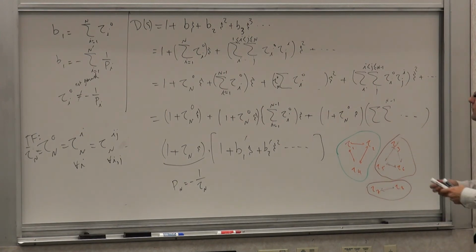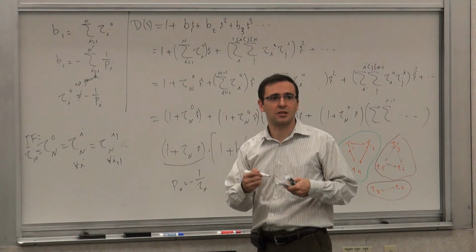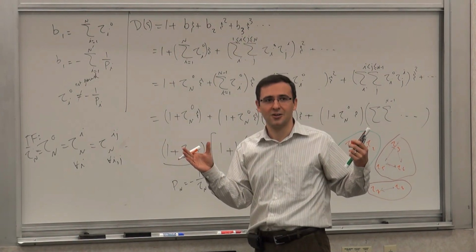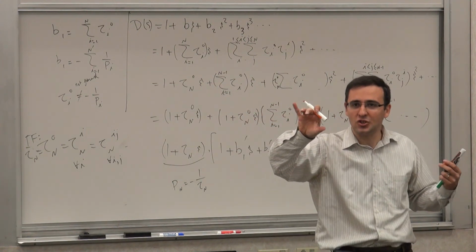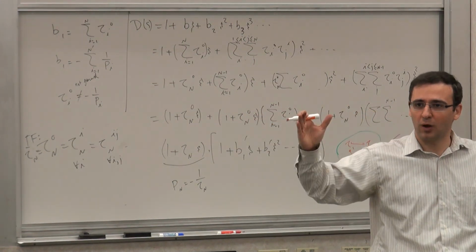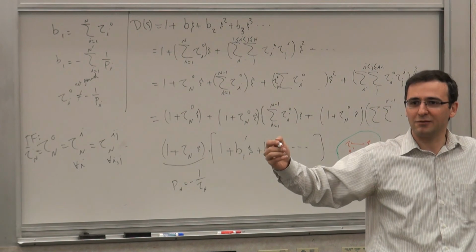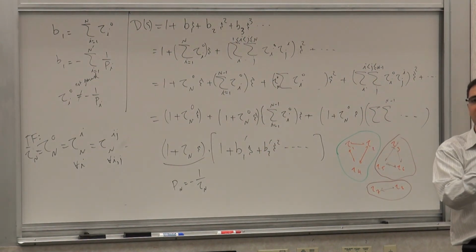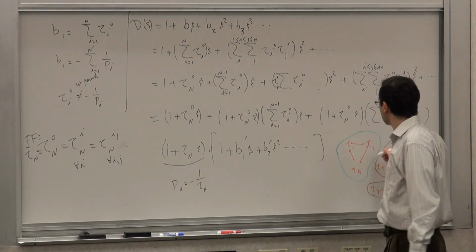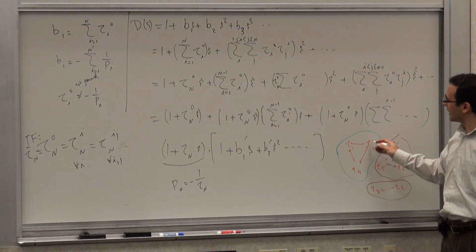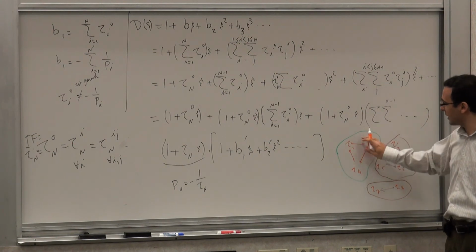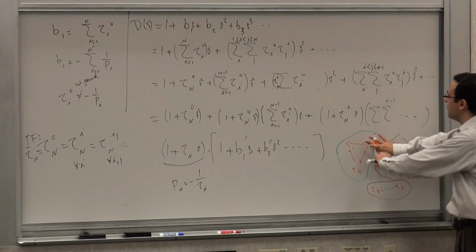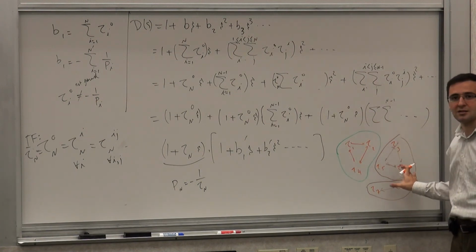What is an example of this? For example, you have multiple stages that are cascaded and they are buffered from each other. They will have time constants within each group that will affect each other and will form polynomials within that. But the overall transfer function denominator is the product of these three polynomials, right? So you can actually find out that these three time constants are interacting with each other, so they're coupled to each other, but they're collectively uncoupled from these guys.